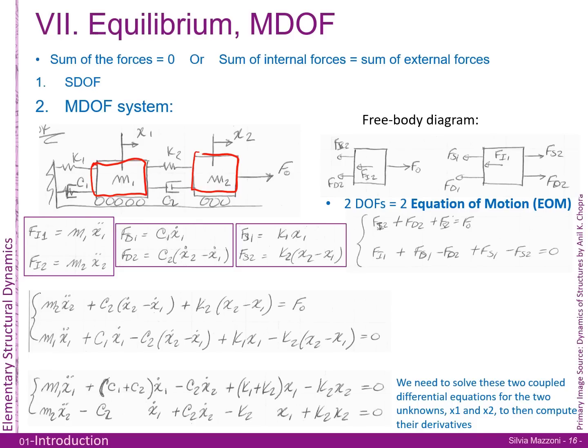So we're going to start labeling things, and this is really important that you get familiar with labels and directions and forces and get comfortable with equilibrium. Very important to always do a free body diagram as you go through your systems to make your life correct in terms of sign conventions, okay? And I know this is something that we're going to be visiting again and again. So we've got these two masses, therefore we've got 2 degrees of freedom. Mass 1 has degree of freedom 1, and mass 2 has degree of freedom 2. We're going to label them x1 and x2.